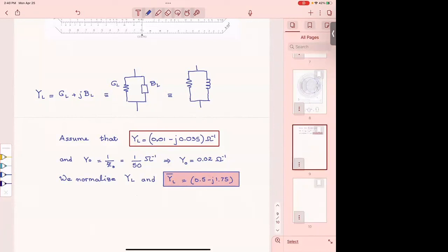All right, let's try to write everything in admittance form. So this is going to be a GL, and GL is the inverse of RL. But I don't need to put RL there, I don't care, because it's parallel. Why would I put impedances when I have a parallel and I need to sum it up? I'll leave it as admittance. However, B sub L in this form here is minus something.